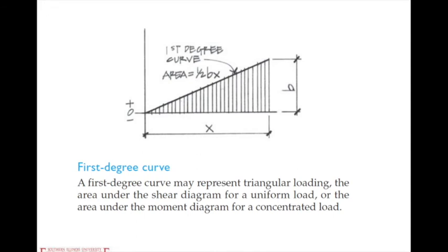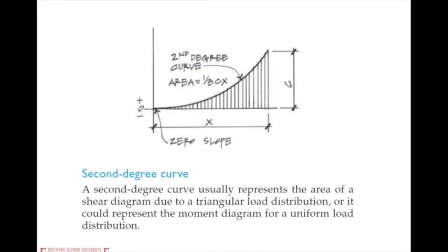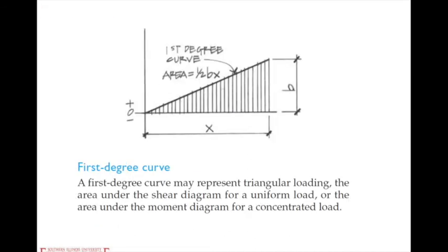Actually, in our future calculations, in order to make our drawing process more efficient, we will have some tabular format, and each basic loading piece will have its related V and M diagram. You can look up this diagram, quickly find what it looks like, and then add them together. We will talk about this later to accelerate our drawing process.